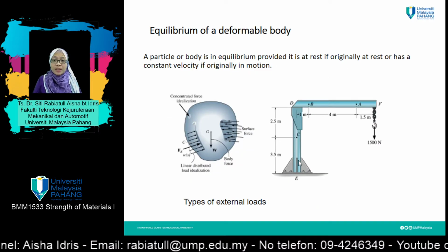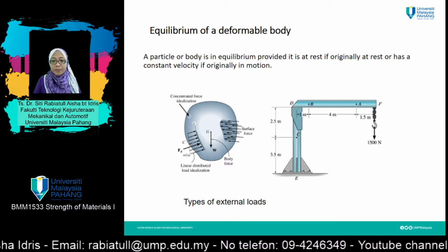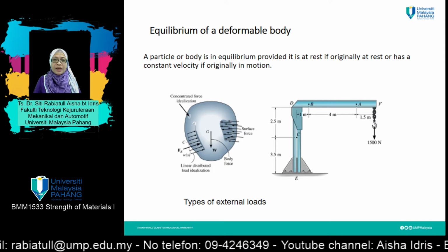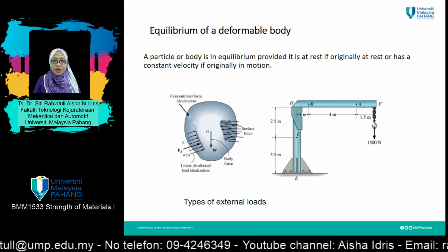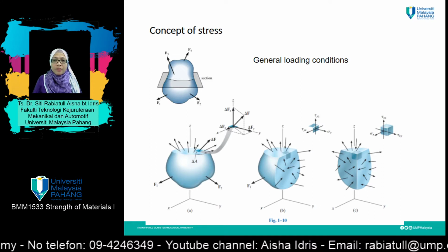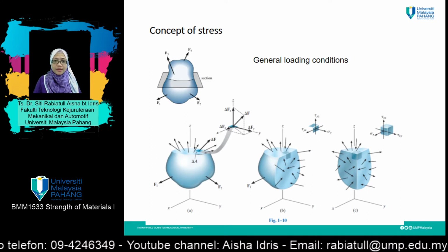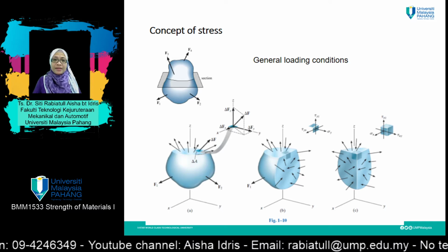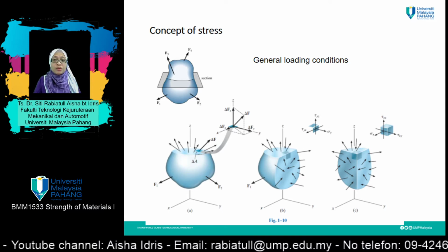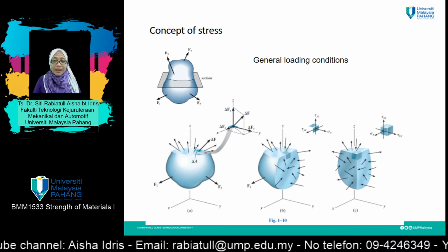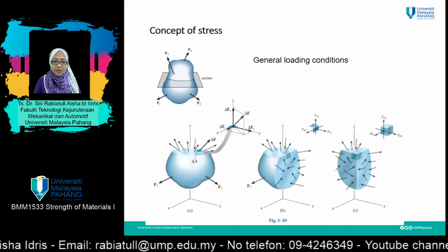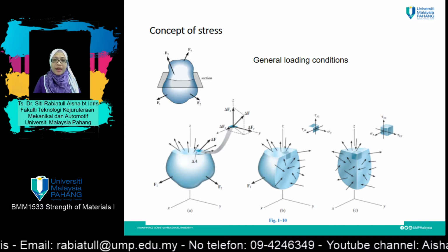As we know, same as in statics and dynamics, every single body needs to be in equilibrium, meaning that the total forces need to be equal to 0. The direction of the forces can be acting at various angles on those structures, and therefore we need to summarize all those forces so that we can calculate and sum all the forces in axes, for example, axis Y, X and also Z.